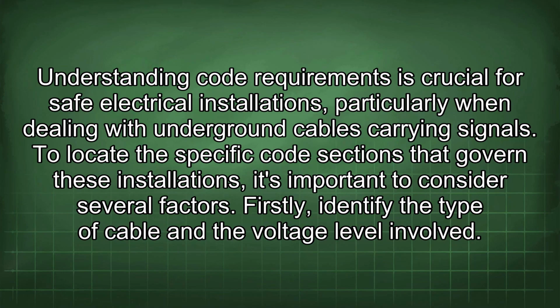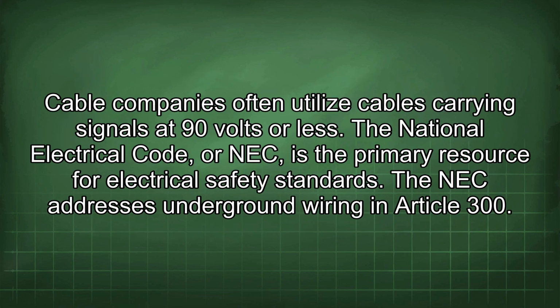Understanding code requirements is crucial for safe electrical installations, particularly when dealing with underground cables carrying signals. To locate the specific code sections that govern these installations, it's important to consider several factors. Firstly, identify the type of cable and the voltage level involved. Cable companies often utilize cables carrying signals at 90 volts or less. The National Electrical Code, or NEC, is the primary resource for electrical safety standards.